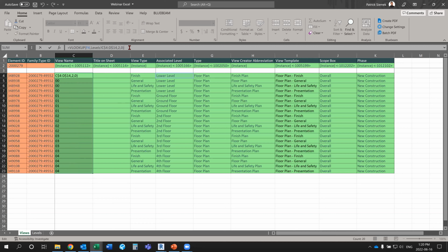As we start adding additional information, I'm going to add a hyphen. So I'm going to type in quote, hyphen, space, quote, ampersand. So now we start to have the hyphen. We could apply that down. We start to add the additional information. The next one that I'm going to want to select is going to be, going to come back into here, going to use an if statement.